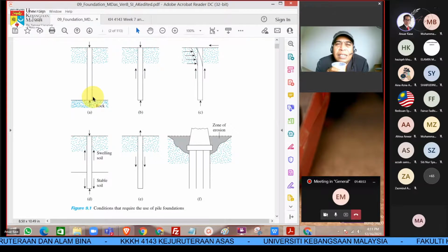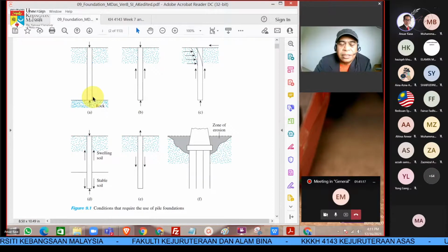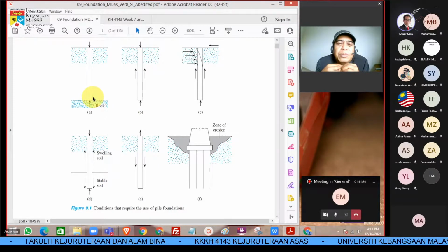Maybe there is a weak soil layer on top, or the soil is so weak that it cannot sustain the load of the structure on top of it by using just the shallow foundation. When that happens, then definitely we are going to need a deep foundation or pile.